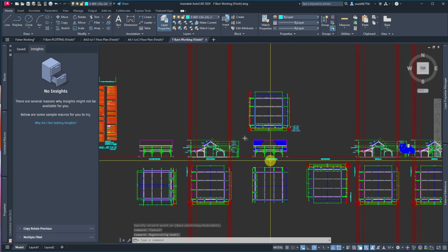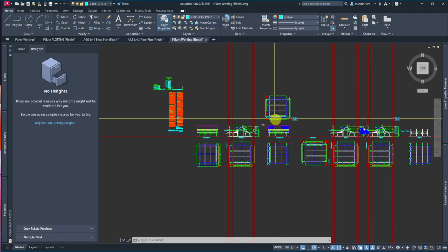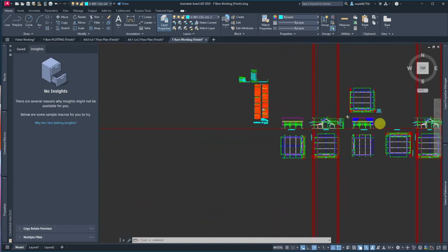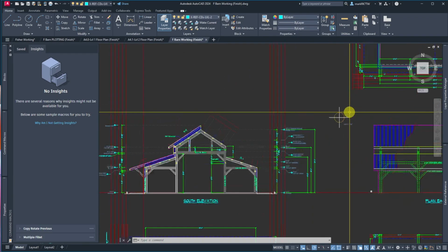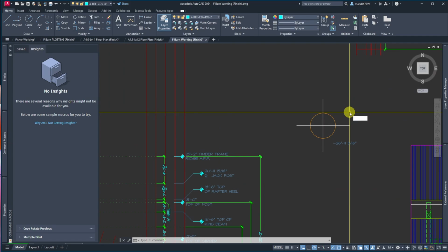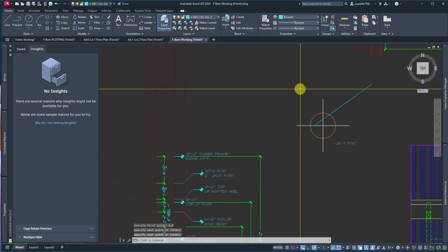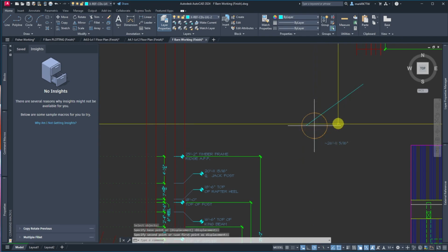So this is the side wall that I chose a garage door. So this should have been lined up on this guy. But we dropped it in on just the 0,0 point. And let's check that point. So if I do a line from 0,0, yeah, see, it got moved. Somehow that got moved. So we're going to move it back to where it belongs.